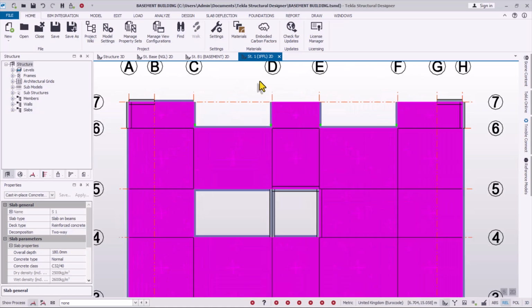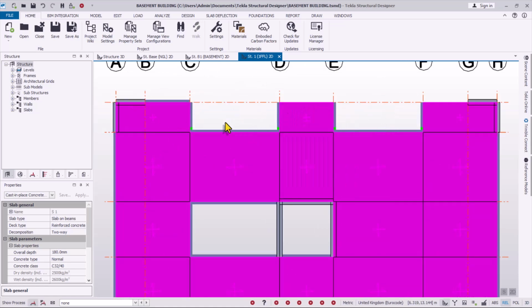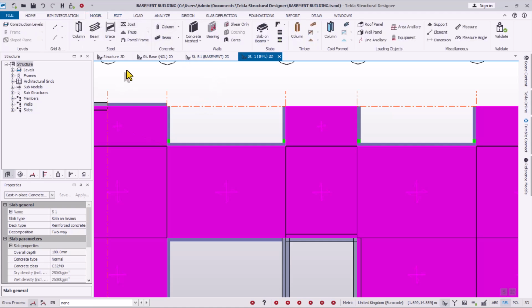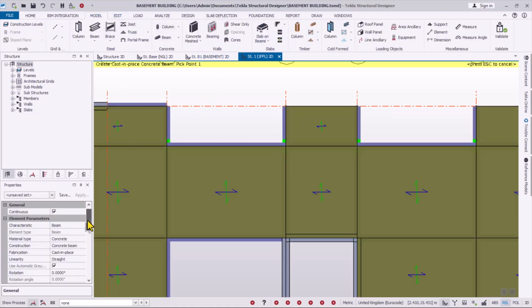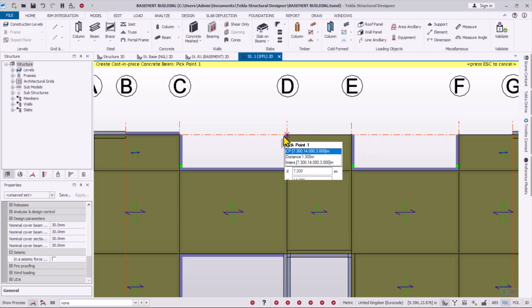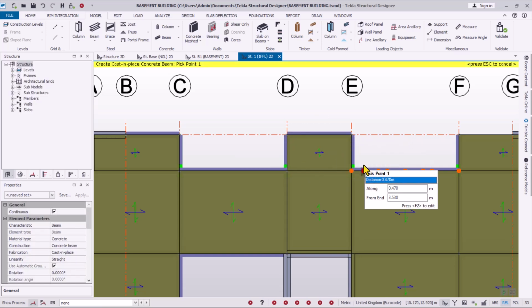All right, so having done this, you can now navigate to the ST1. At the ST1, you can see where we removed beams right here. So we need to apply another beam. Of course, you have to go to the modeling tab and then come to beam options, and then the beam depth we used is 225 by 500, which is this beam depth. Everything is good right here. Okay, so now we just have to pick from this point, double click right here, and double click here to have the beam placed.